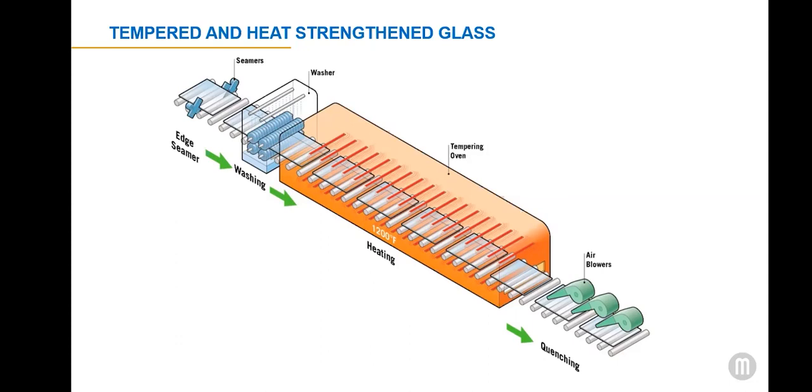The flatter finish also results in less optical distortion in building facades. It has excellent breakage characteristics and prevents fallout. As a result, heat strengthened glass is often used in curtain wall facades in both vision and spandrel applications. In some situations, though, heat strengthened glass is not suitable. For example, when safety glass is required for human impact safety, you'll have to use tempered glass.